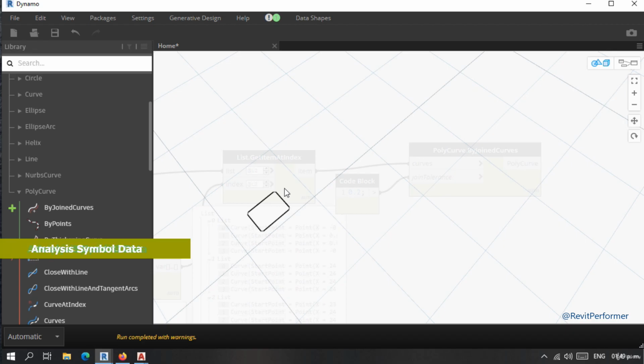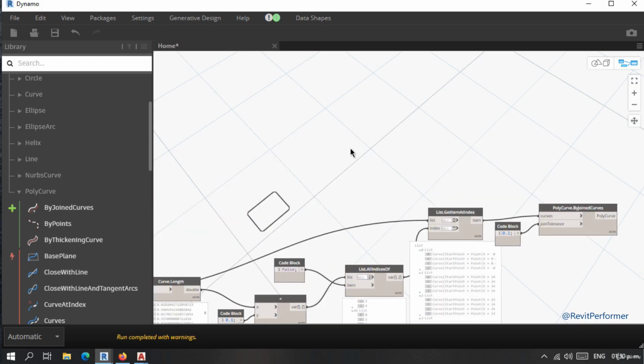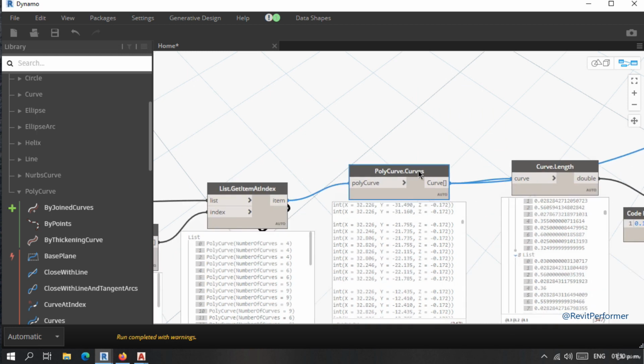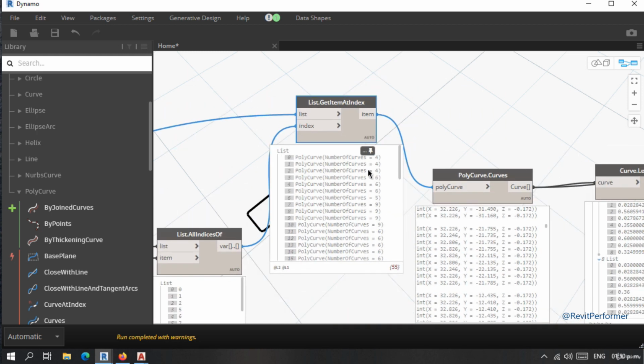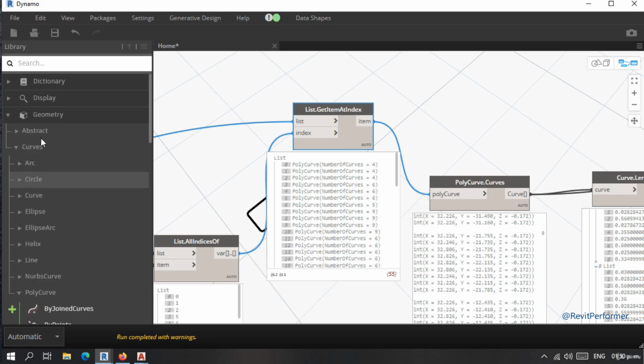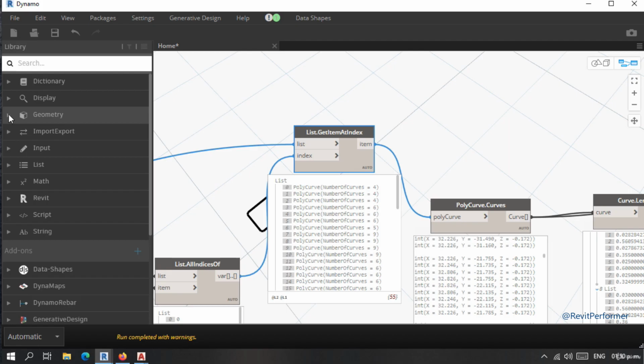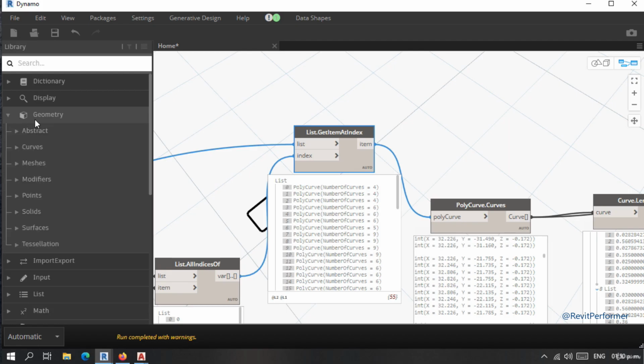So we can do it differently. We can have elements being pulled to be just a square, or we can separate them through the family they are requiring, or just create the geometry. So let's see the three scenarios. Okay, so thinking of this, we can create the geometry just by the polycurves we have here. If they are already polycurves, that means that we can also copy them depending on the height we require or the elements.